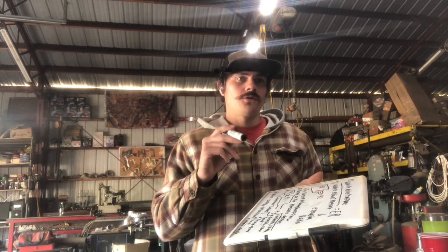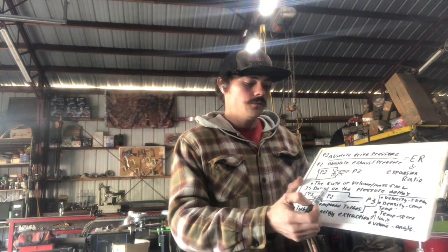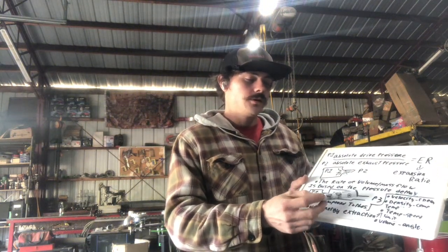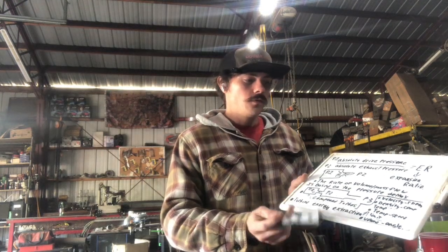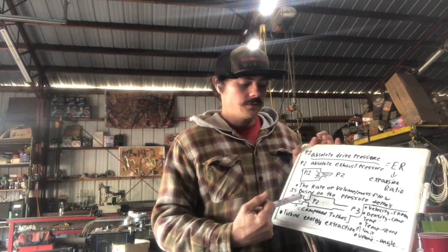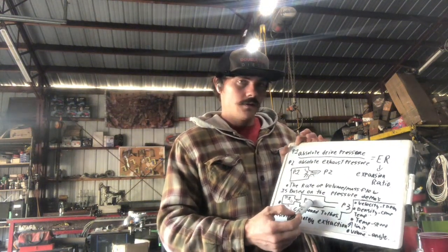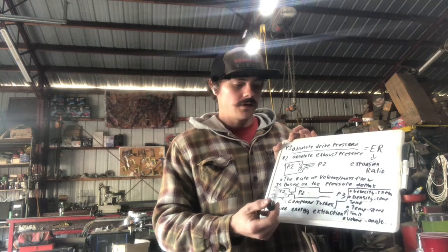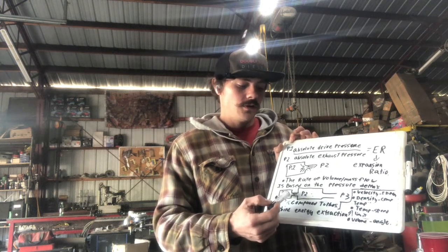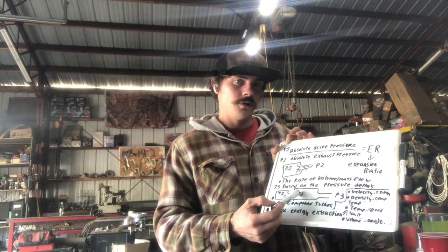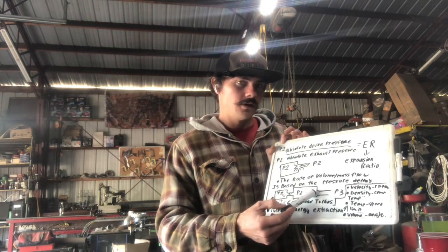So the more restrictive the manifold charger is on your P1 to P2, the smaller the atmospheric charger can be. The more your manifold charger flows, the less restrictive your atmospheric needs to be. Because if your manifold charger's exhaust side flows too much, your P1 and P2 pressures will get too close together. All the load will sit on the P2's turbine side.